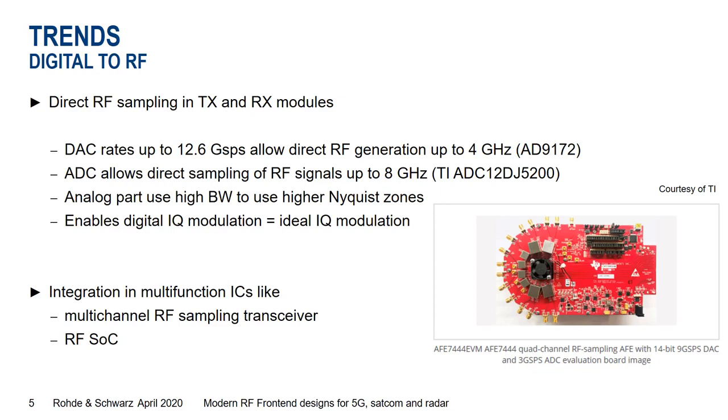The IQ modulation, which is done basically 100% digital, is in the end an ideal IQ modulation. There is no nonlinearity, no distortion based on the IQ modulation, which we see on classic analog IQ modulators.